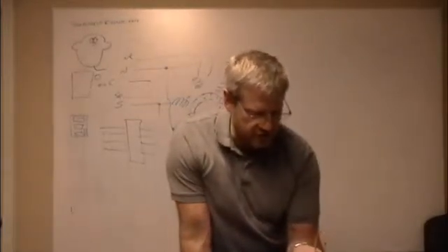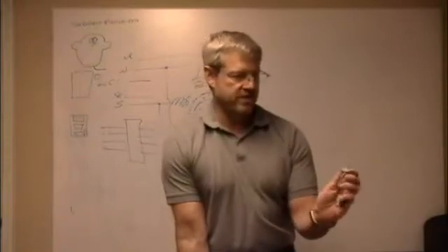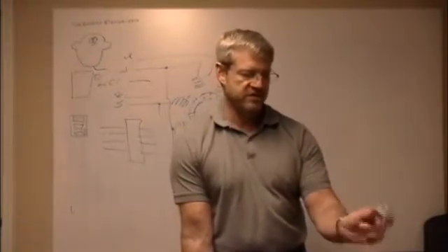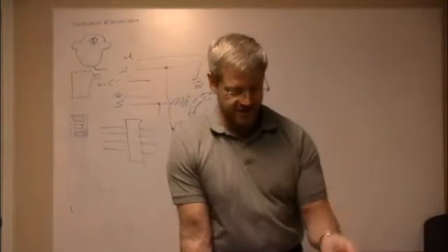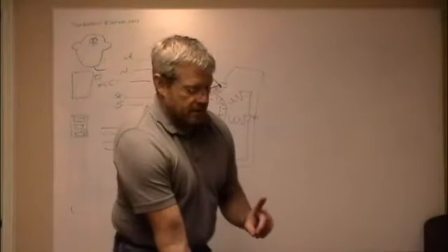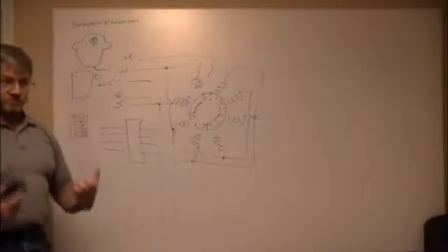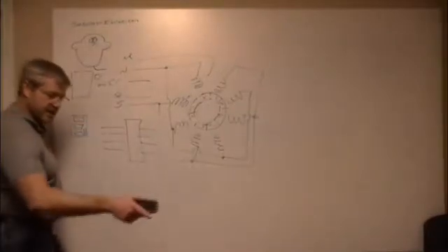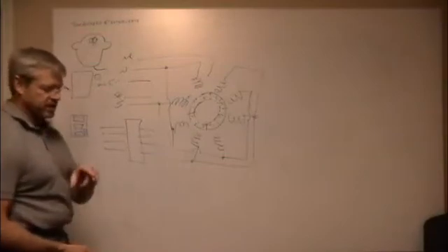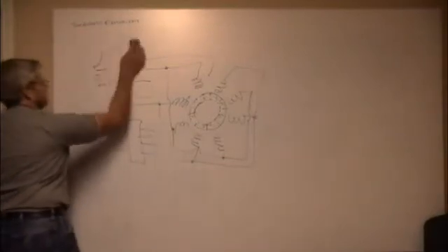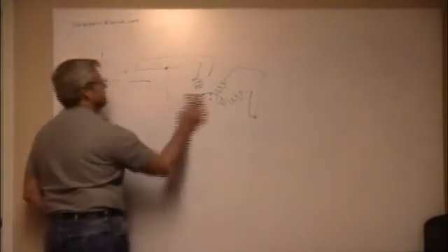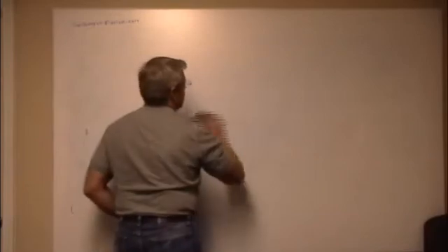Now the other kind of controller that you can buy. So these are cheap hobby controllers. This, you would not make a 3D printer out of this. It just does not have the torque you need. The other kind of controller, I've got some of these at home that I'm using. These are big. They can drive 3 amps on each coil. That little guy can drive, I think, a half an amp on each coil. You can buy these on Amazon for about $14 just for the controller. Or on eBay, if you look around, you can get them for about $6 or $7.